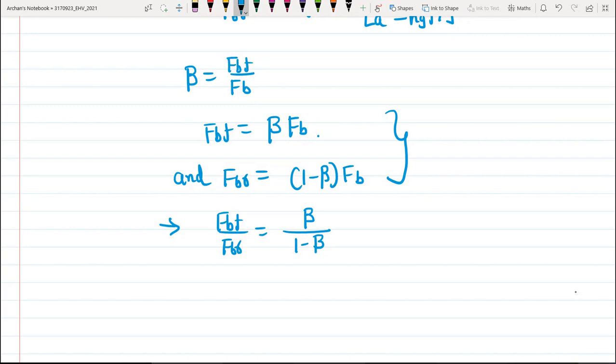Therefore, designers of vehicle brake systems must ensure that the rear wheels do not lock up first. Nowadays we have ABS, the anti-lock braking system, developed in recent years, which can effectively prevent wheels from locking up. This system employs speed sensors to detect the wheel rotating speed. When a wheel lockup is detected, the braking pressure control system reduces the pressure and brings the wheel back to its rotation. This is how our braking system works.